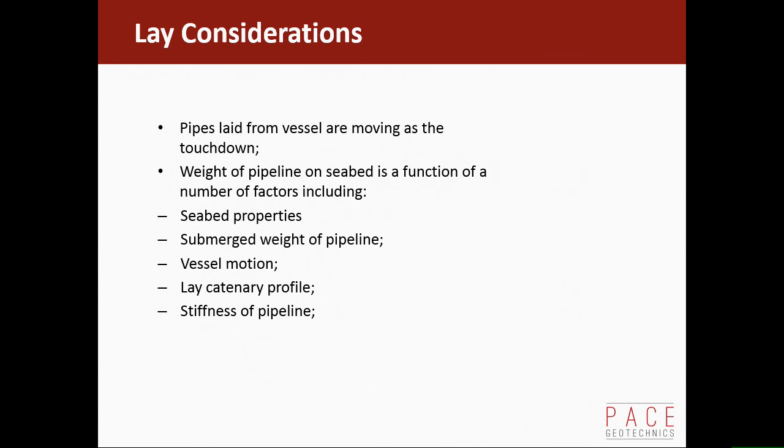So, lay considerations. What do we have to consider when we actually lay the pipeline on the seabed? The pipe's laid from a moving vessel, so they're moving as they touch down on the seabed. You're familiar with J-lay and S-lay, are you? Yeah. The weight of pipeline is a function of a number of factors: the seabed properties, strength of the seabed soils, the submerged weight of the pipeline, also things like the vessel motion and the lay catenary profile, and actually the stiffness of the pipeline.